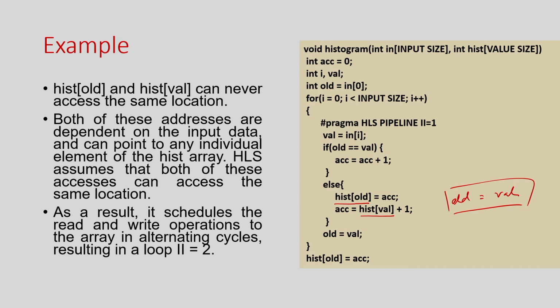So in this execution order it will write first and then read. This is basically a write-after-read kind of dependency. It will try to obey this dependency and schedule the write first, and then in the next clock the read. As a result I cannot parallelize these operations, which is correct in that sense, because if you just do it in parallel you will get the wrong value.